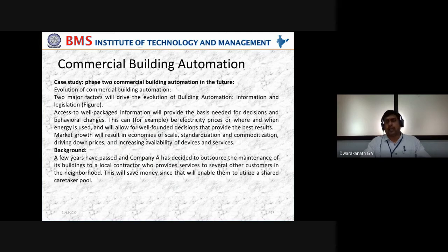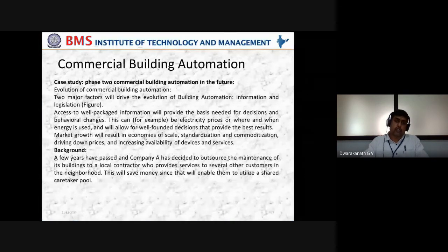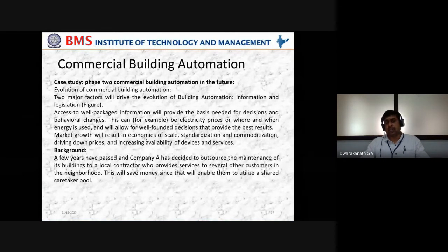After installing a package, IoT automation and all, assume that you have reduced your electrical bill by 25%. Why? Because you have used PIR sensors and LDR sensors, based on motion and light. You are controlling your entire lighting system through mobiles and a central control system, where you can switch lights on and off even at night if somebody has left them on. So definitely it will reduce the energy, meaning the electrical bill.